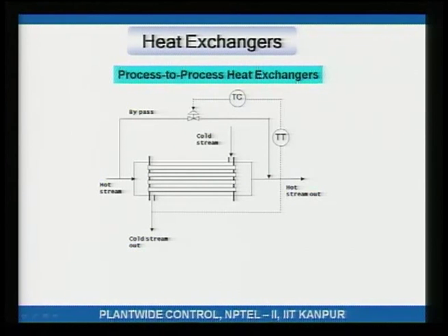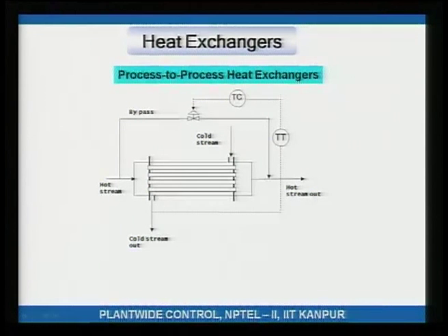However, for the tubes to become hot or cold, because less or more material is flowing through the tubes, that will be a slow process, that will take a long time. Okay. So, the temperature control in this configuration won't be very tight, right. So, that was about heat exchangers.